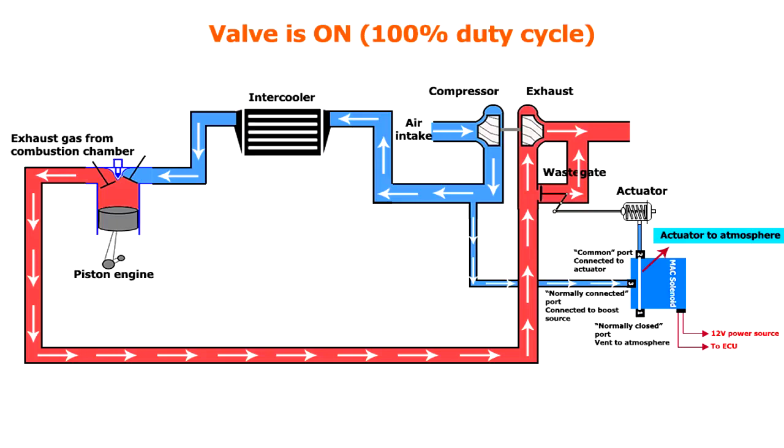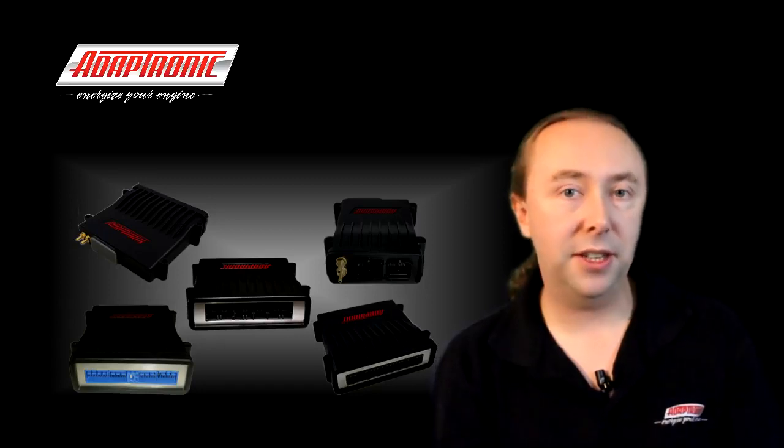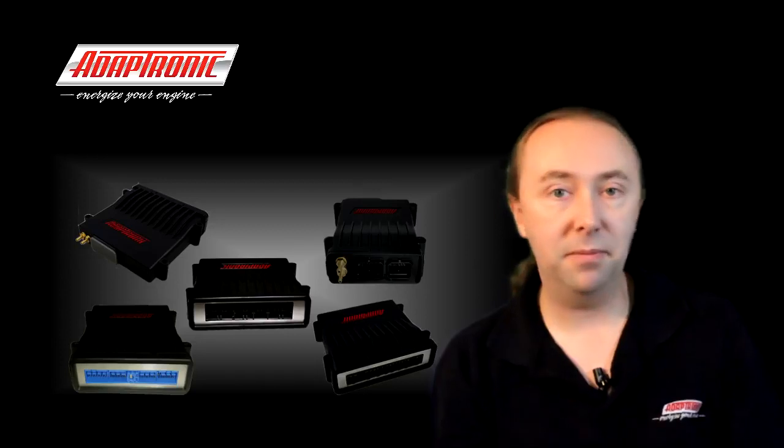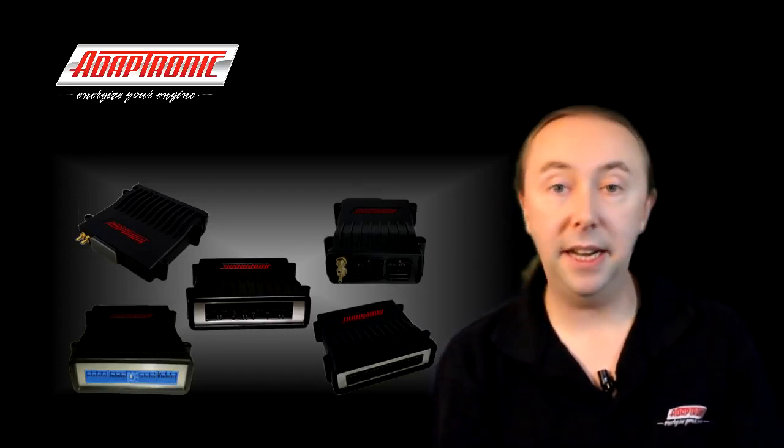Now the normally closed port of the valve vents to atmosphere, so if you give the solenoid 100% duty cycle and turn it on completely, then the actuator actually doesn't see any boost at all, and in theory the wastegate then remains completely shut. So that way you can adjust the boost pressure anywhere from the wastegate boost level up to infinity, or as much as the turbocharger will make. And by pulse width modulating it, you can get somewhere in between.